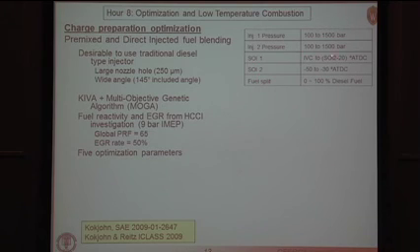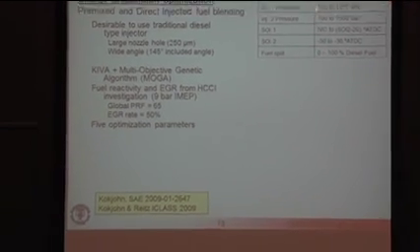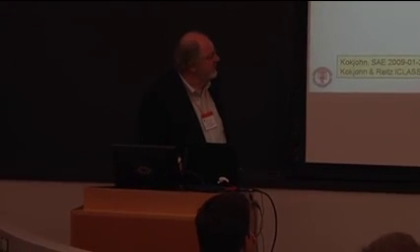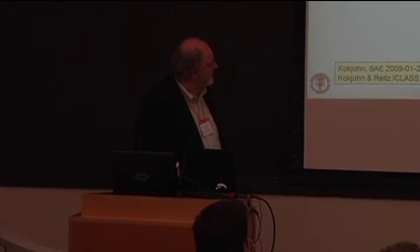We're going to have injection timings that go all the way from intake valve closure up to close to top dead center, and this one, the second injection, up to 30 degrees before top dead center. And we'll allow basically the amount of fuel in the 2 injections to go from all the fuel in the first injection to all the fuel in the second injection.